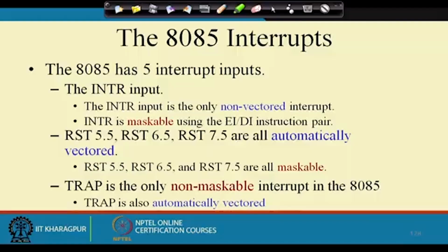When the power goes, the system is held on the battery, so the system should first try to save all the critical data. The trap service routine may be doing that. It will take note of all the critical data in the system and their values, copy them onto some save locations, and then go into a power down mode. That way, TRAP can be used for very critical situations.